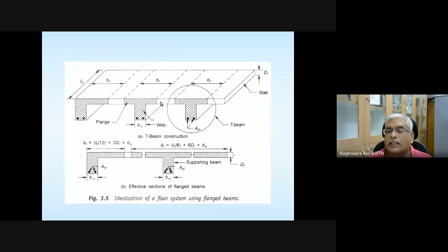So if the neutral axis is within the flange, or exactly flush with the bottom of the flange, or passing through the junction between the flange and web, then the area in compression is going to be either the overall flange area or a part of the flange area.